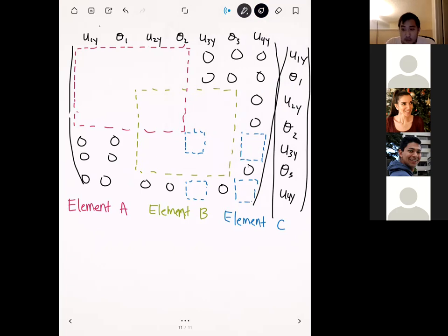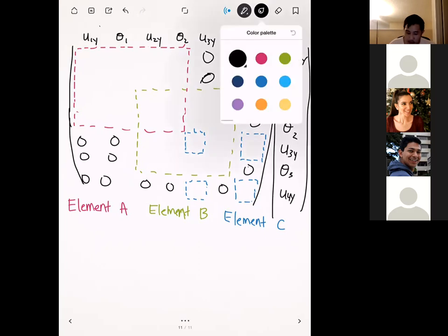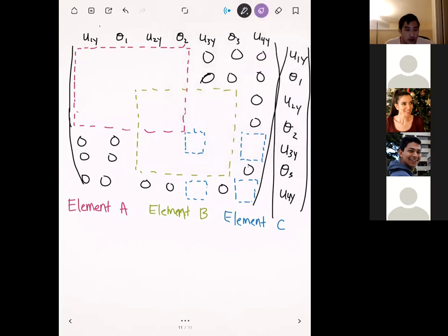All right. And so just like before, you can go ahead and fill in all the entries in the matrix according to your element stiffness matrices, okay? Here you have to be careful though, because we have two different element types. And so don't forget that for the beams we have our coefficient in front of EI over L cubed, okay? And so make sure you're punching those into your calculator correctly, because then once you apply the spring, the spring doesn't have that EI over L cubed out in front, okay? Because the spring is just K. And so make sure that you account for both of those once you're filling in the matrix. Okay. All right. So any questions on the assembly?